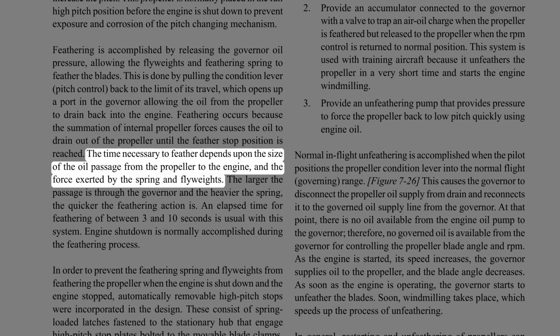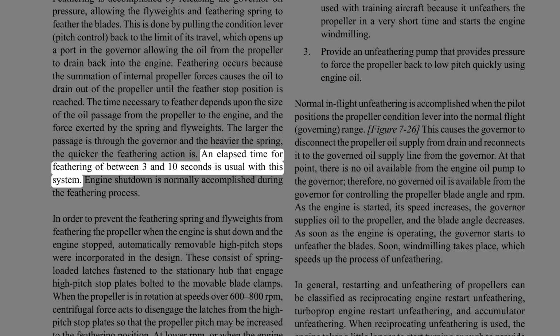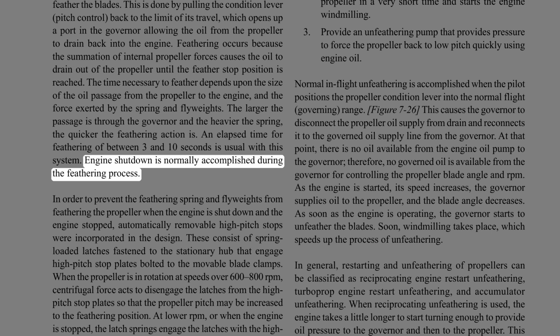The time necessary to feather depends upon the size of the oil passage from the propeller to the engine, and the force exerted by the spring and flyweights. The larger the passage is through the governor and the heavier the spring, the quicker the feathering action is. An elapsed time for feathering of between 3 and 10 seconds is usual with this system. Engine shutdown is normally accomplished during the feathering process.